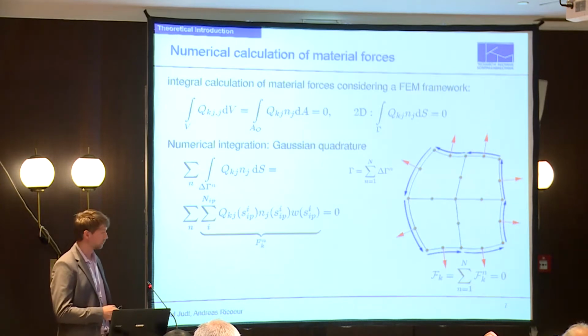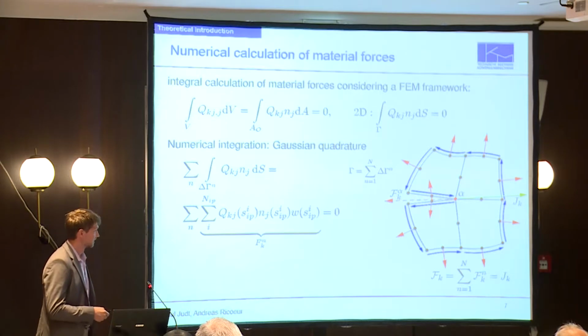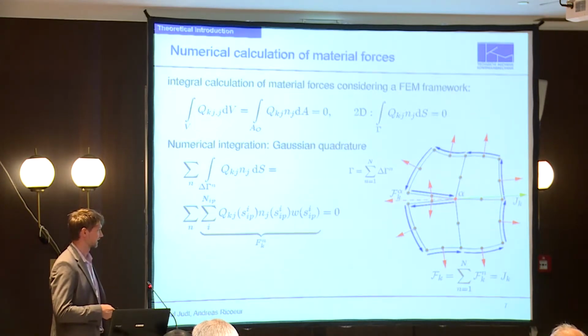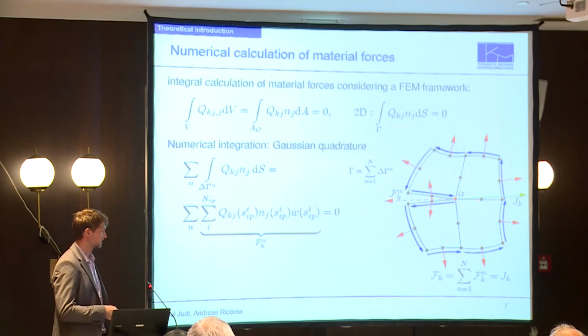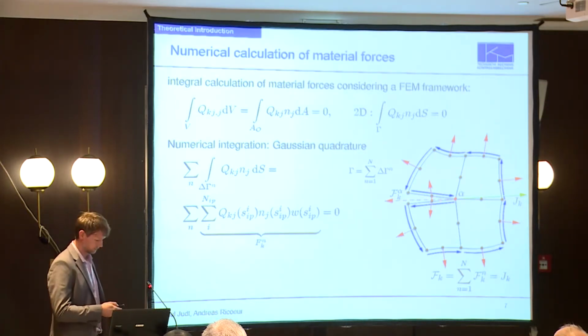The same holds if we have more finite elements, and again, if we have a crack, then we need to consider the integration along the crack faces as well. But we cannot capture the material force at the crack tip with this integration. Therefore, what results here is the crack driving force, which is nothing else than a J integral, and this is what we use in the following.